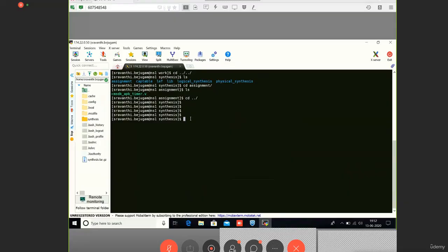As I mentioned, in the run.tcl file I have given the paths from the working directory. If you want to give other paths also, you can give the pwd command where your path is and copy paste that path in your run.tcl file. So your base directory will be the work directory where I have created the paths.